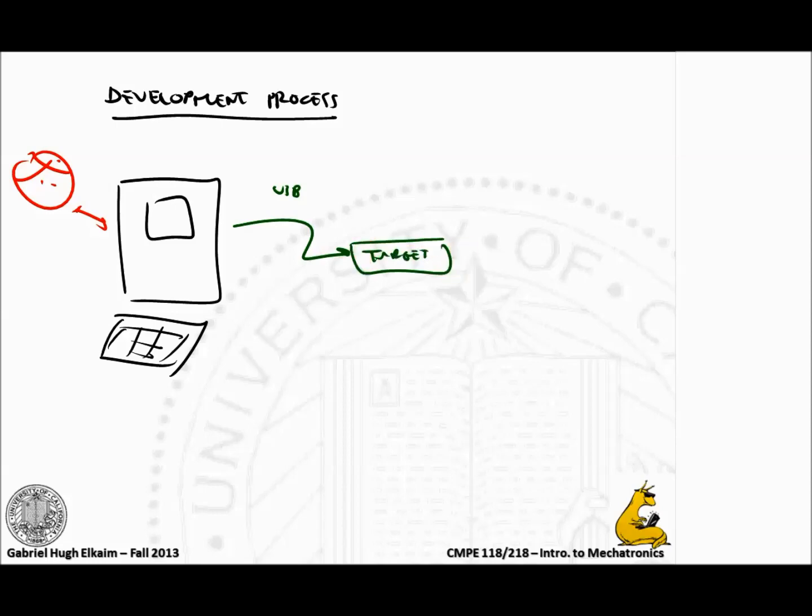And then if you're lucky, on the target you have some form of monitor, or in this case, a serial to USB. We go back along the same bridge that lets you know what's going on inside it. There are lots of different kinds of monitors you can get. There are things called ICE, in-circuit emulators, where you have this big snorkel thing that comes down from the PC that actually fits on the PCB and looks like a microcontroller. It usually clamps onto the pins of the microcontroller and takes over everything.